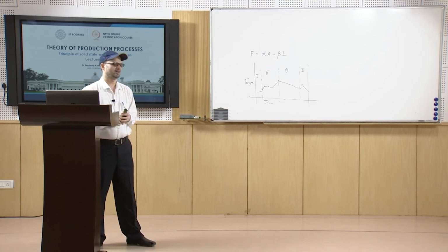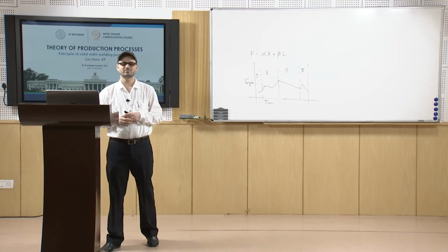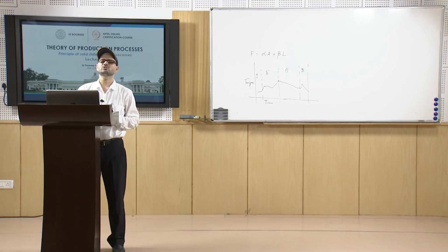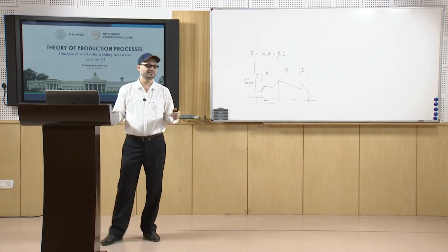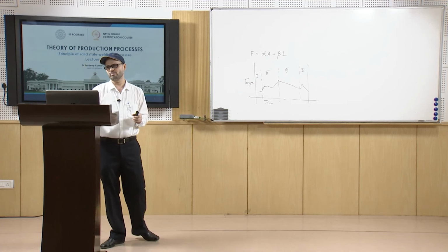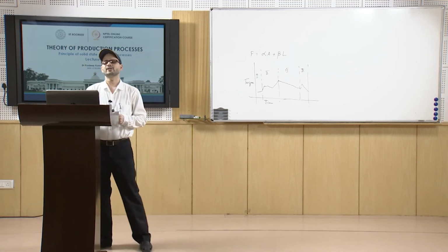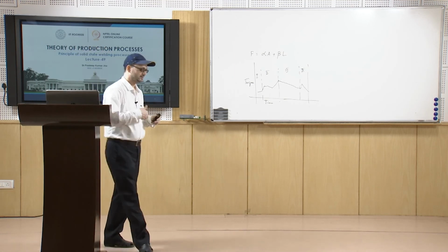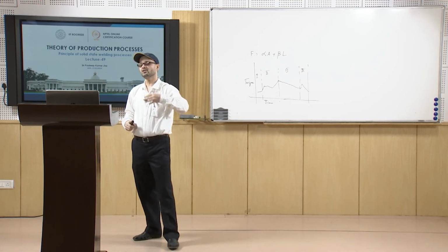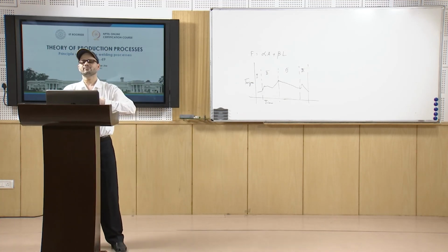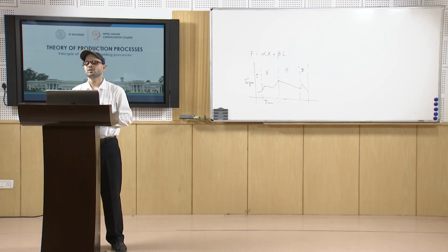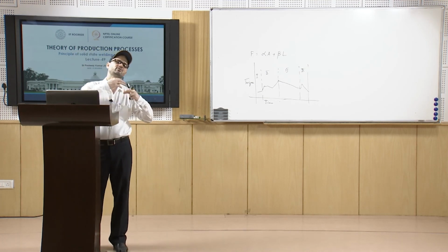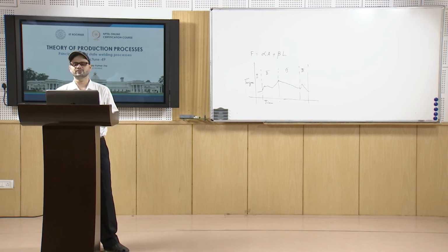Normally aluminum alloys, aluminum copper or aluminum copper lithium alloys, are mostly used, and it has been proved to be very successful. Very small energy requirement is there in this case, only for the movement and some clamping pressure. So it is a very energy efficient process as compared to other joining processes like arc welding or even resistance welding. There are many advantages: no need of filler, minimum joint edge preparation, no embedded oxide formation possibilities, and good joint strength.